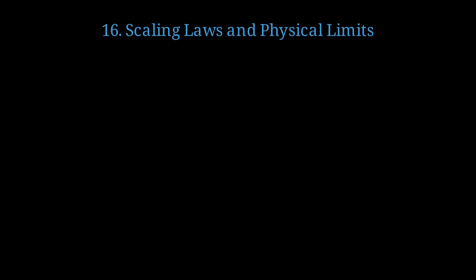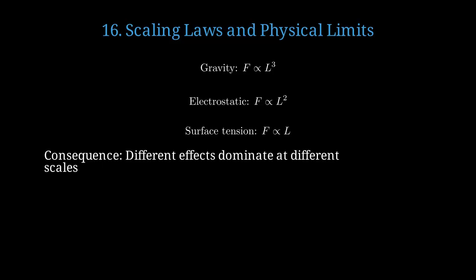Understanding how different effects scale with size reveals natural application domains. Gravitational forces scale with volume, proportional to length cubed. Electrostatic forces scale with area, proportional to length squared. Surface tension forces scale linearly with characteristic length. This scaling behavior explains why different physical effects naturally dominate at different size scales,